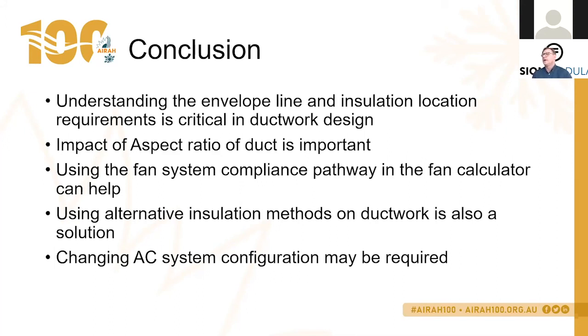So I cannot confirm nor deny, but I would, in certain situations, possibly use that solution myself, but I would not use it in too many applications. I'd prefer to go rigid duct and then just standard flex. It's a bit easier to install, you get less air leakage problems, you get less performance issues, etc. But yes, so up to you as a designer.